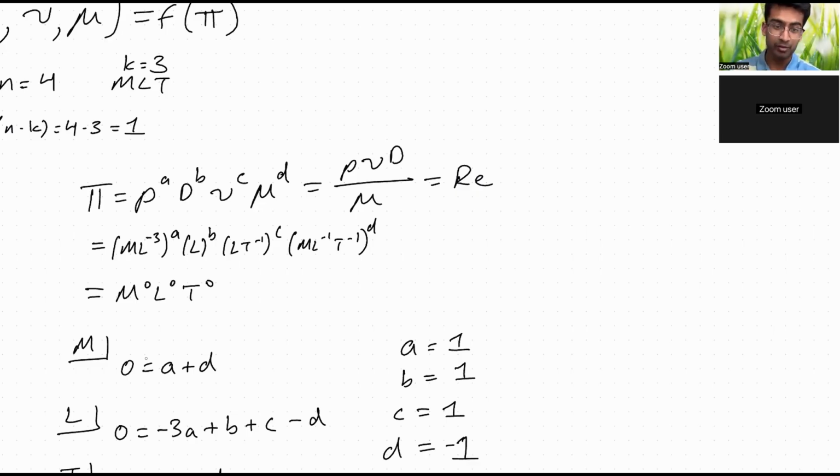If we have a pipe in the lab that's running at 30,000 Reynolds number, when we scale it up to a larger unit, say a production unit, in order for the flow properties to be the exact same, we have to have a Reynolds number of 30,000. Again, we have to have them equal at both scales.